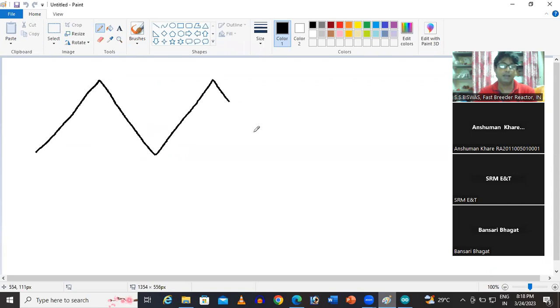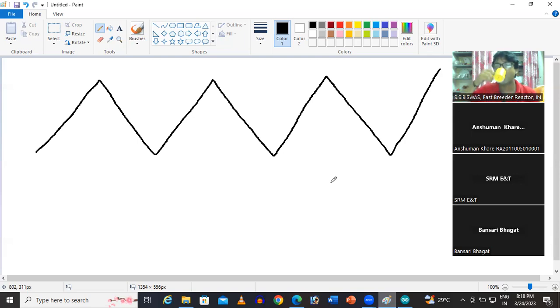That is called phase correct mode. But there is another mode, called fast PWM. In fast PWM, it will go from the initial value to maximum, then suddenly come back to the initial value, not in a slope. It will fall sharply, perpendicularly. That is called fast PWM.